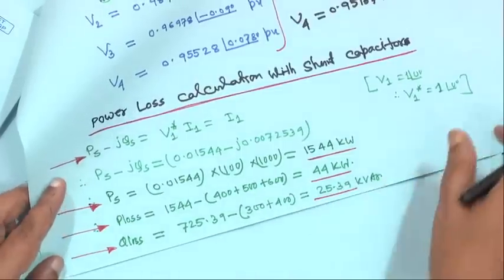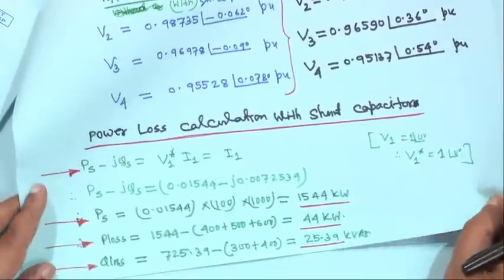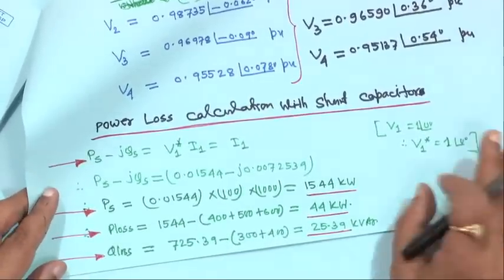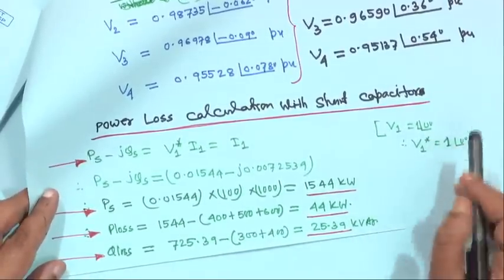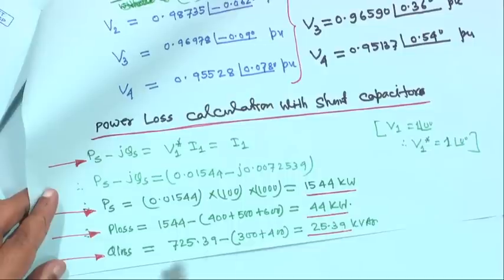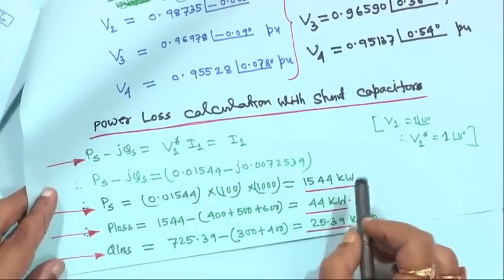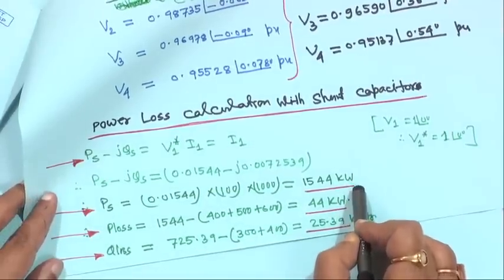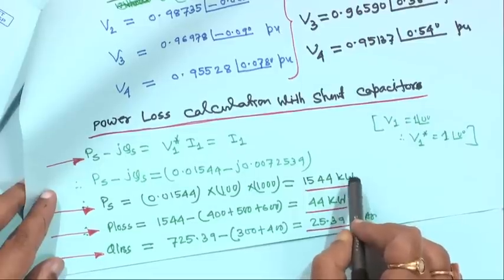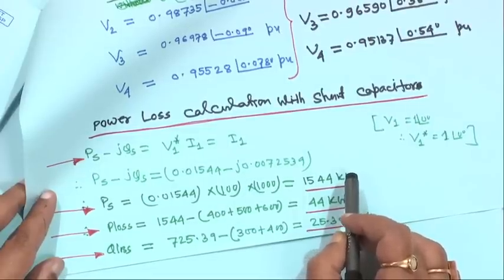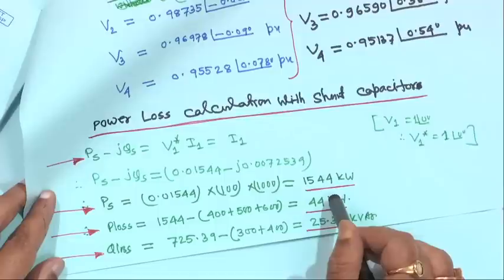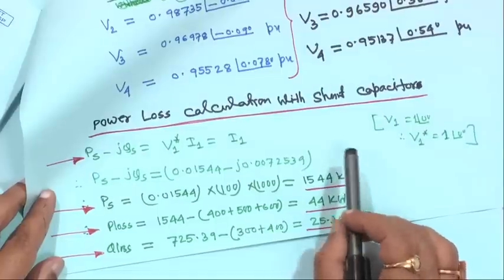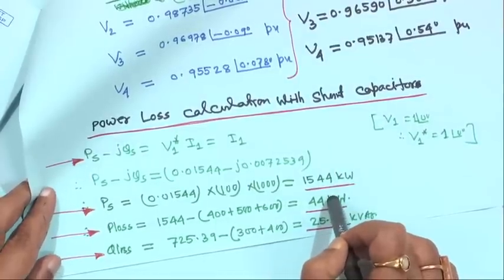If you go to any substation anywhere, although it may be there on the 33 kV side or 66 kV side, in distribution systems also you will find that utilities all over the world are putting shunt capacitors, at least 2, 3, 4 shunt capacitors. For that they try to find out the best location.